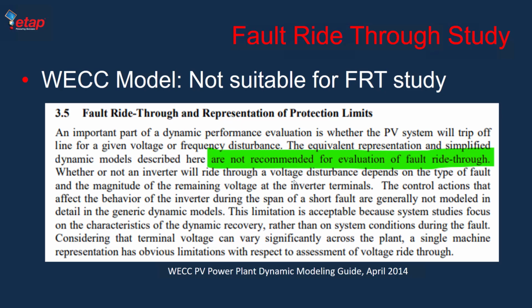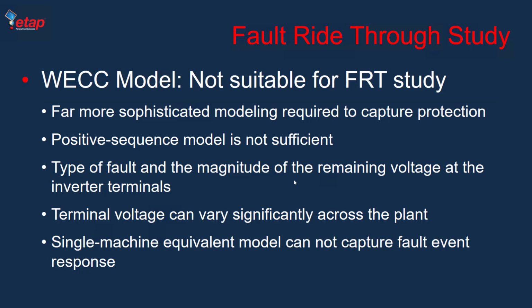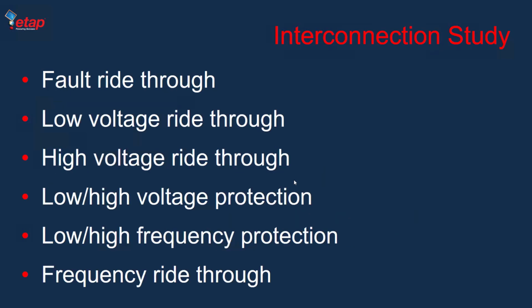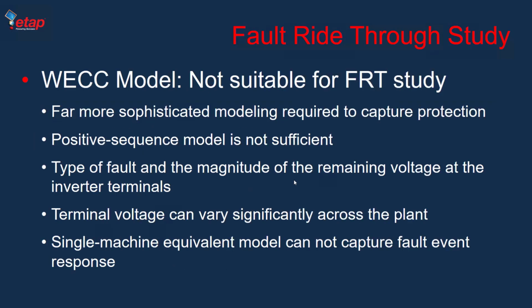If you use a generic model, you're just verifying a generic model performance, even though they haven't developed too much around the FRT capability. And again, when it comes to interconnection study, the fault ride-through, low voltage, high voltage ride-through, or even a little bit of frequency ride-through, is all you need to use vendor specific. When it comes to protection, you can actually model the protection independently. If those protections are outside the inverter control, just dedicated relays, you can model them in ETAP and evaluate their performance.